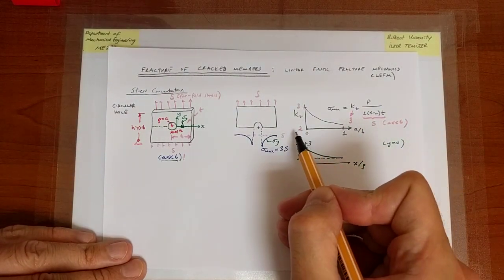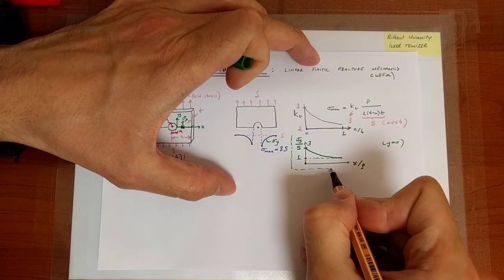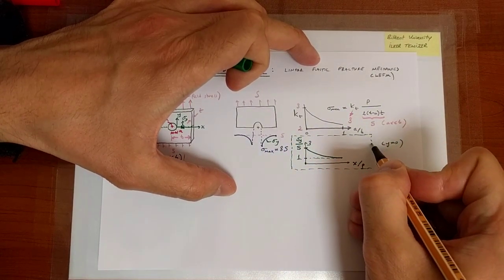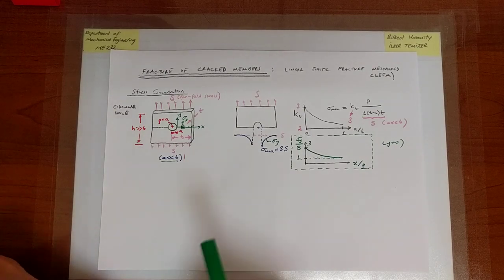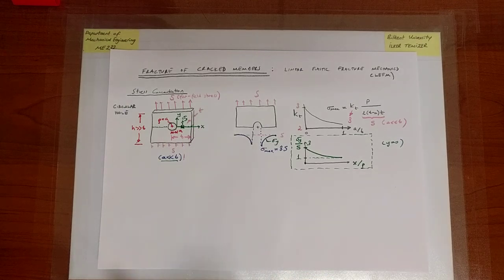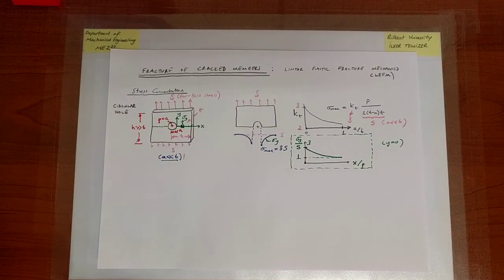Let's also keep this picture in mind because eventually it is going to be useful for us in a moment to think about how the stresses vary when we have a hole with a slightly different shape. On the side, you may wish to remember that the thickness is largely irrelevant in most of the upcoming discussions because the thickness does not influence the stress concentration factor.